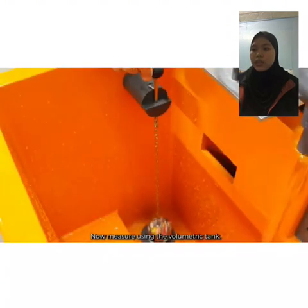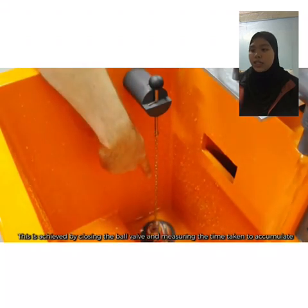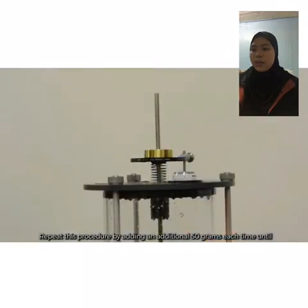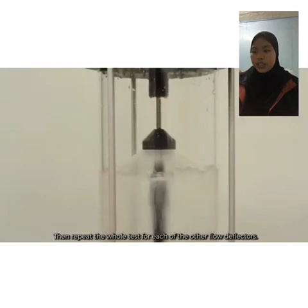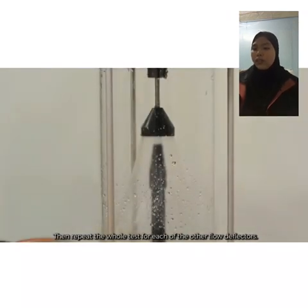Now measure using the volumetric tank. This is achieved by closing the ball valve and measuring the time taken to accumulate a volume of fluid in the tank, as measured from the side glass. Repeat this procedure by adding an additional 50 grams each time until the maximum weight of 500 grams is reached. Then repeat the whole test for each of the other flow deflectors.